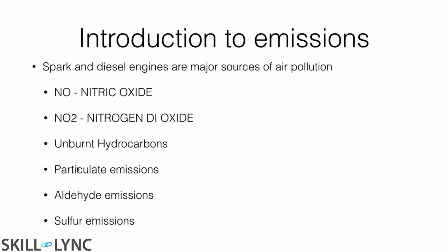The idea behind particulate emissions is that these are emissions where you actually get particles. Now these particles are really, really small. They are on the order of nanometers. And the problem is they can cause serious health hazards. These particles are so small that they can cross your respiratory system very easily and can cause long-term damage if you have prolonged exposure. And oftentimes you might have heard of the term soot, S-O-O-T. Soot comes under the classification of particulate emissions. There are other types of particulate emissions which we will see, but soot is the most important.